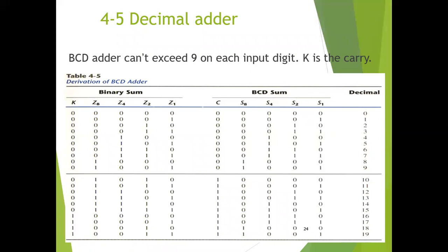An adder for such a computer must employ arithmetic circuits that accept coded decimal numbers and represent results in the same code. For example, for binary addition, it is sufficient to consider a pair of significant bits together with a previous carry. As we can see in this table, a decimal adder requires a minimum of 9 inputs and 5 outputs.